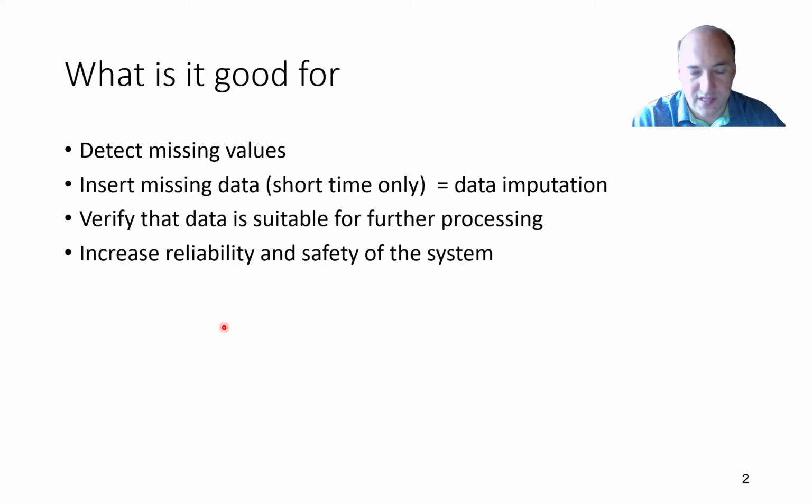It will obviously depend on the sampling rate, because for some systems you will need a sampling rate of, for example, 1 minute. You don't need to sample faster. But for some other systems you may want to sample every second or every millisecond. So there is no specific time that you can say that this method will work, but it will be purely related to your sampling time.